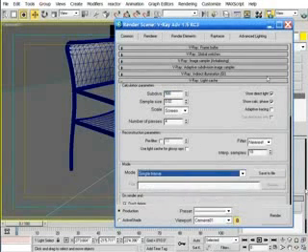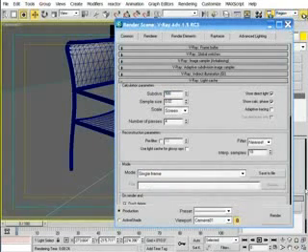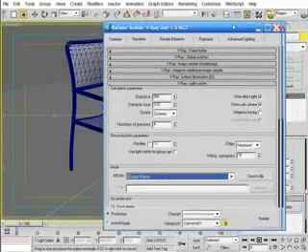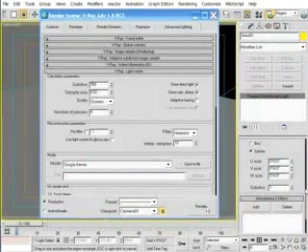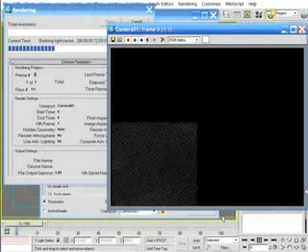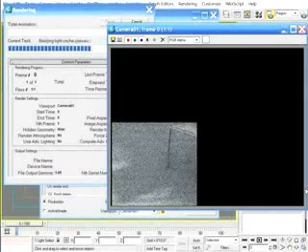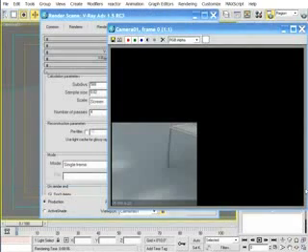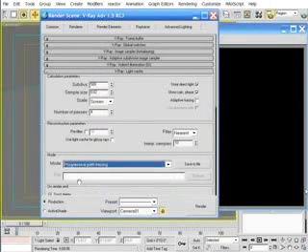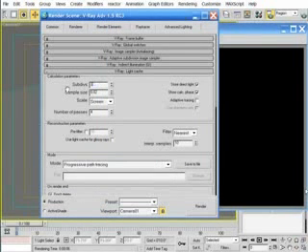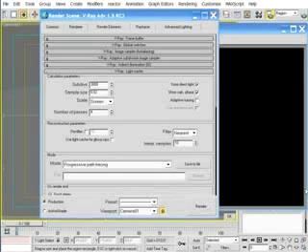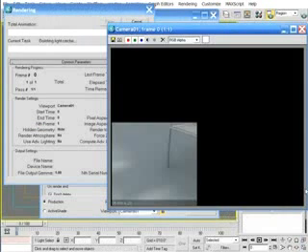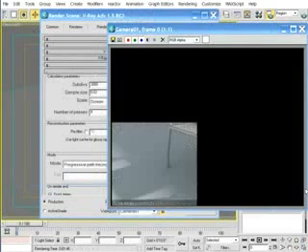And notice here, when I render this region using light cache in single frame mode, a subdivision value of 1 for the sun's shadows results in a great deal of noise. Well, when I switch to progressive path tracing and use a decent subdivision value, I get noiseless shadows.